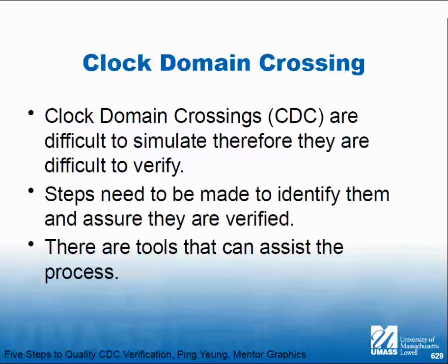Now, what does that really mean? Well, I don't know what it means anymore because I used to know what it meant when I put an analog oscilloscope on it and the value was somewhat proportional to the value that it was seeing. Now we don't have analog oscilloscopes anymore. We have digital oscilloscopes, and digital oscilloscopes produce discrete results. It might not look it, they might filter it so to your eye that it isn't, but digital oscilloscopes sample things. Remember last week, right? So simulators are the same way.